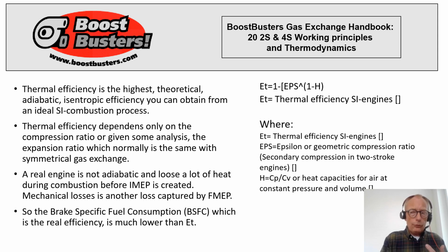And that is what's taken care of later when we come to the real, important fuel efficiency, which is sometimes also called the brake-specific fuel consumption. And when you recalculate that and compare it with thermal efficiency, it is about half of what you can expect from the theoretical thermal efficiency based on the compression ratio, or more correctly expressed, the expansion ratio of the engine.